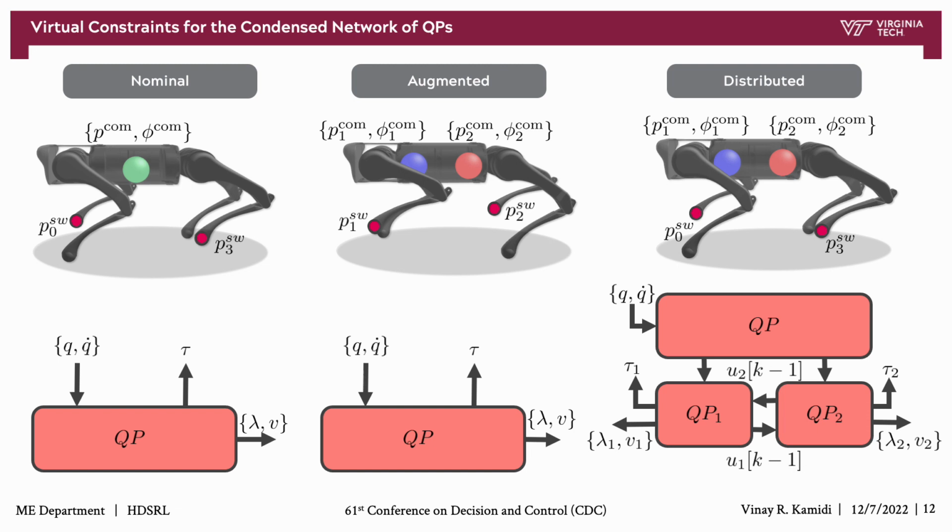the augmented formulation. More specifically, 6 outputs are designated for the Cartesian coordinates of the center of masses for the front and hind subsystem, and the remaining 6 outputs are redundant and reserved for the absolute orientations of the center of masses. The last 6 outputs are reserved to control the Cartesian position of the two swing leg ends. To address the redundancy in orientation and to ensure the validity of the full rank assumption, we introduce slack variables to the QP formulation. This ensures 9 virtual constraints are available for each subsystem, as shown in the figure to the right.